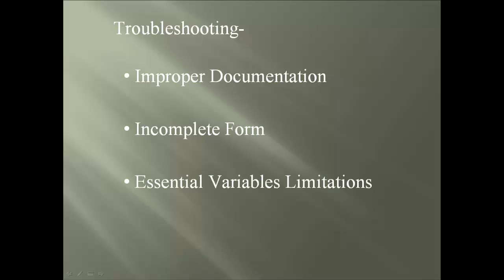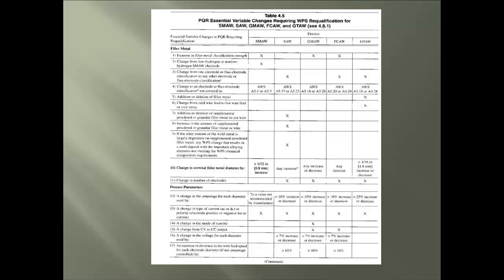And here is a very important table that is new to the 2010 D1.1 code, which sets the limitations for a PQR that may require the WPS to be requalified. Here we see the new table for the 2010 D1.1, and there are 3 pages that cover the items dealing with the PQR.